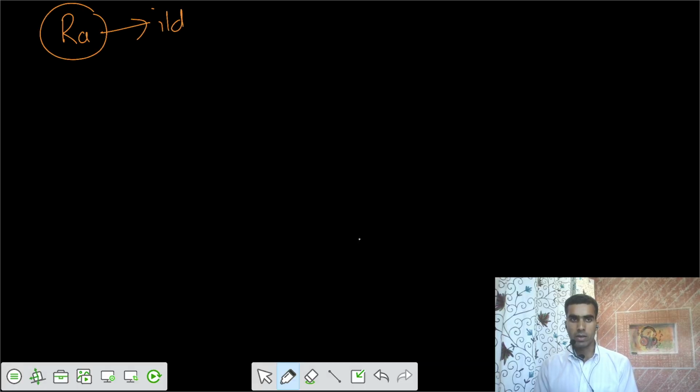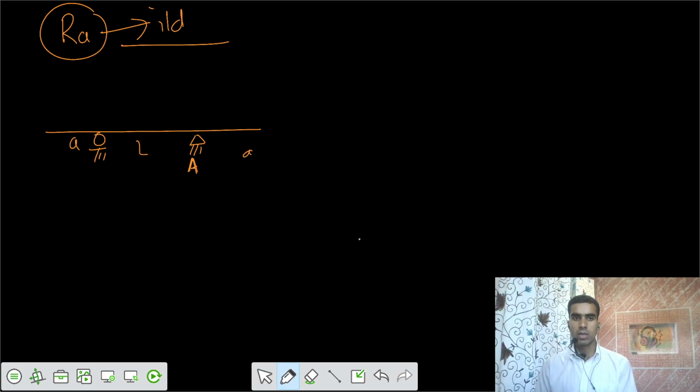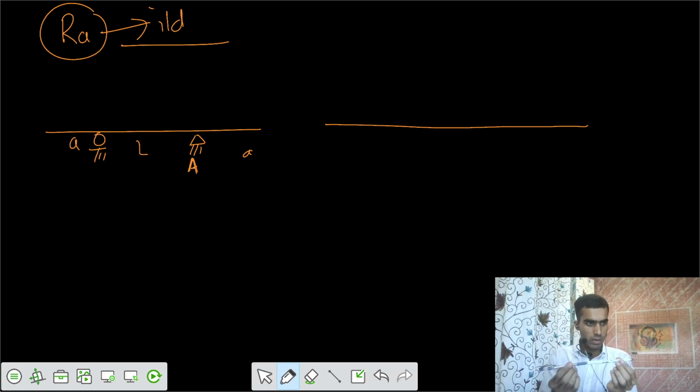Let's get the ILD for reaction at A in these problems. Say the first beam is a double overhang beam, and we have support A here. This length is L, and the overhang is a. We need to get the ILD for reaction at A. This is our reference line, this is our beam, support A is this one, this is some other support, and we have two overhangs.